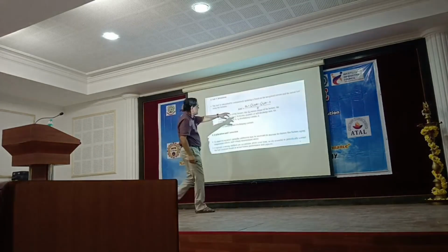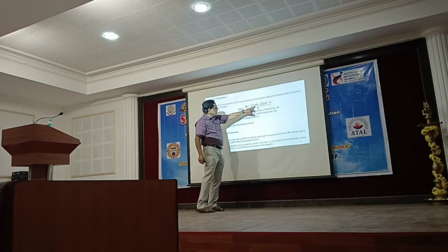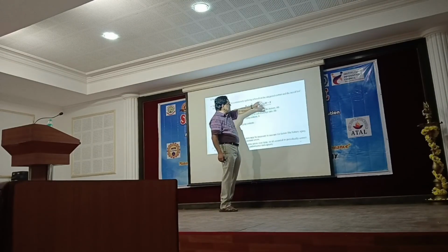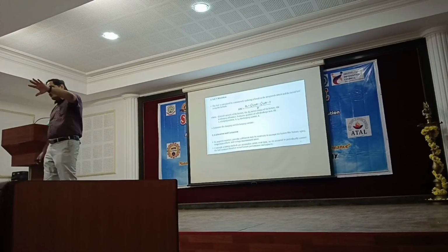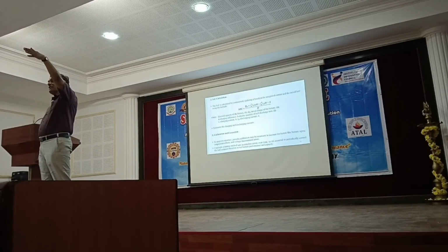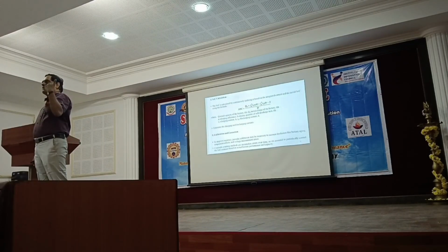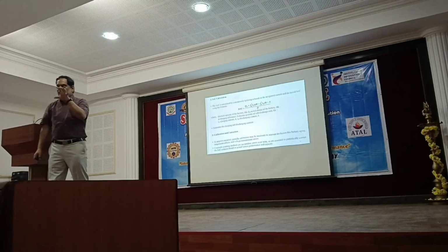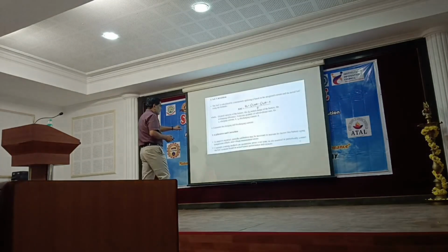So here you have SOC estimation, Q0, already mentioned rated capacity, current, overvoltage, time, and again you see you are integrating from starting to time. How much time do you take for complete charging? The SOC can be estimated during charging also. At what rate you are achieving 100% SOC, and when you drain out also, depending upon at what rate you are draining out, I can estimate. At what rate you are draining out the battery to depth of discharge being 5%, 10%, and so on. And you will never drain out the battery completely. Will never go there.